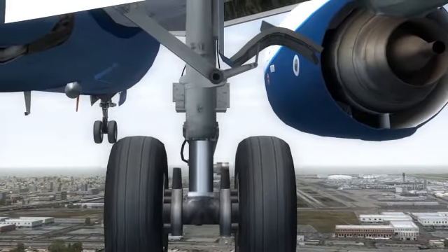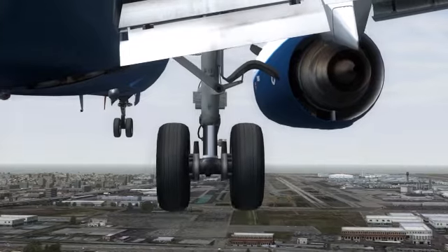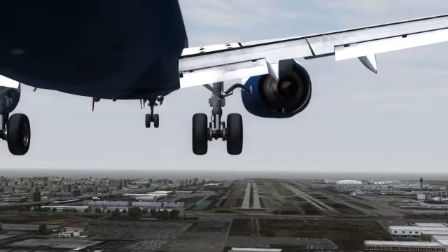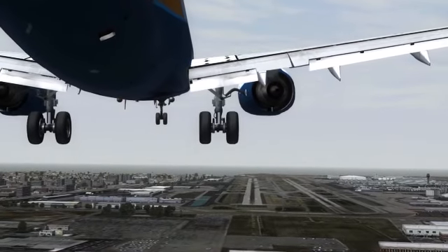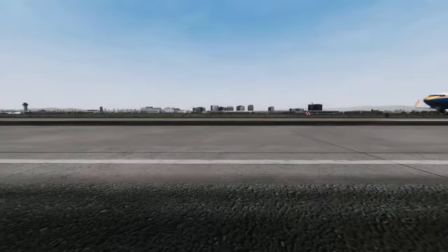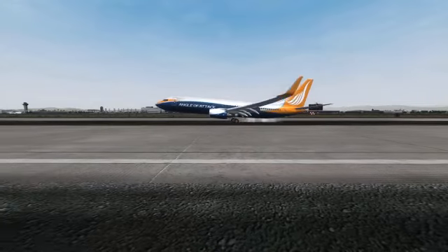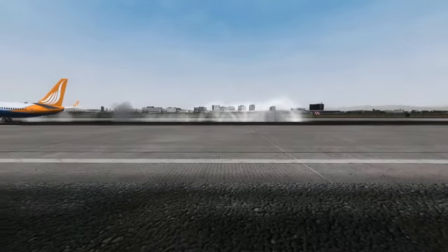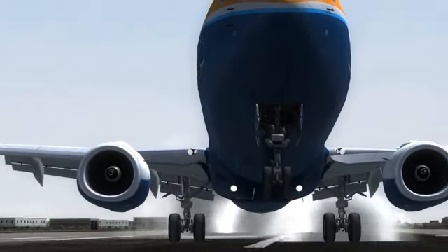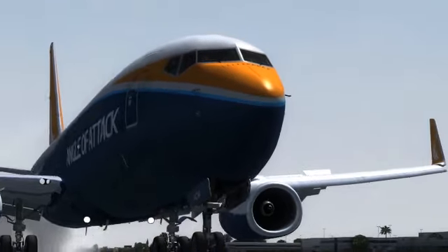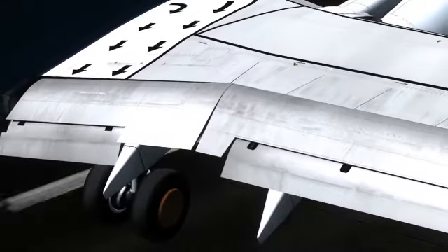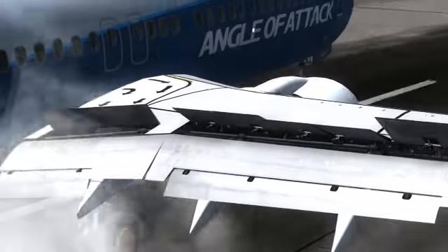However, there is still some sort of forward pushing moment that the engines generate, which is in the order of 20 to 30% N1. This is not favorable to slow the airplane down to a safe taxi speed. Therefore, the pilots engage the so-called thrust reversers. The thrust reversers essentially change the direction of engine exhaust air to help decrease airspeed after a landing or during a rejected takeoff. Usage of thrust reversers is also beneficial to the gear and brakes, as lesser wheel braking action is required to stop the aircraft in the same distance.